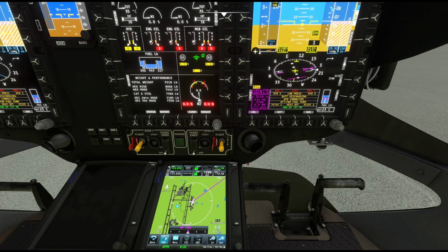If you're in between these two, then you will not intercept that localizer before you actually get to the ILS station. All right, and then here's your FMS. This is going to point towards that right there. All right, and now if I change over my nav source, now my nav source is pointing that exact way. It's telling me that I am set to navigate towards that, which is in line with this. All right, so we talked about that.